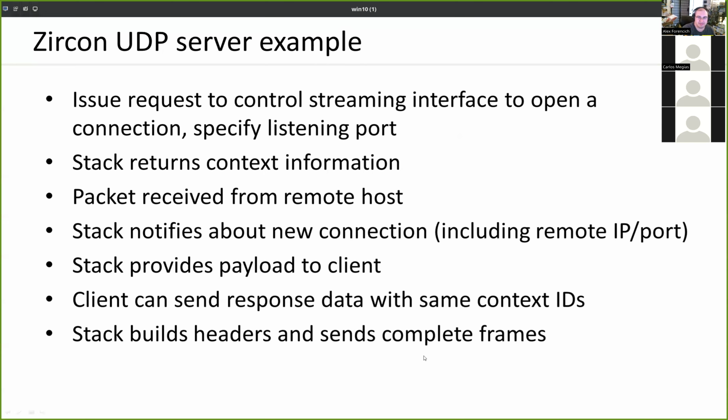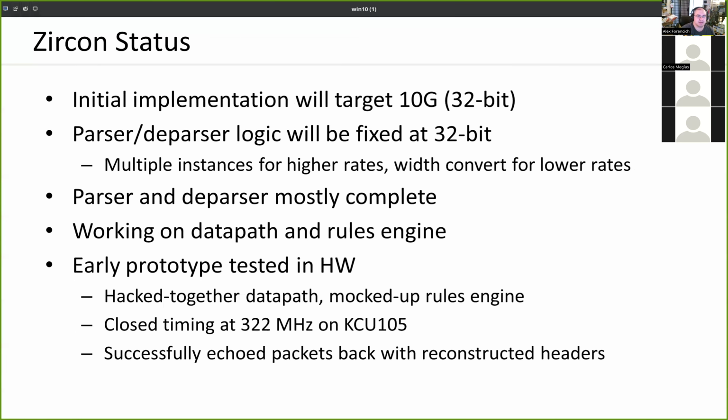But yeah, the idea is that the stack will be responsible for assembling the higher layer headers and computing all the checksums and whatnot, so the user logic doesn't need to handle that. There are some other wrinkles involving things like VLAN tags that may need to be addressed as well. But that's the high level idea.